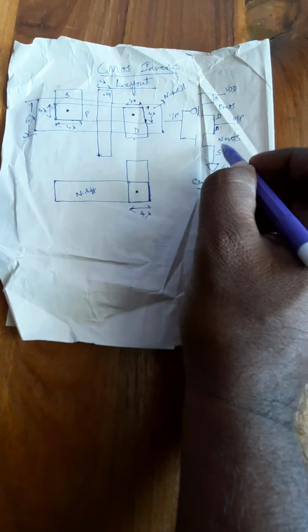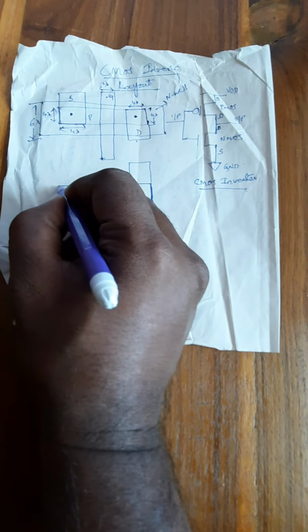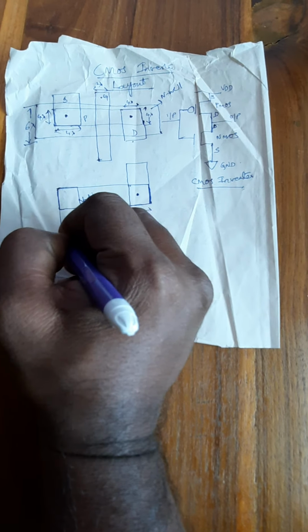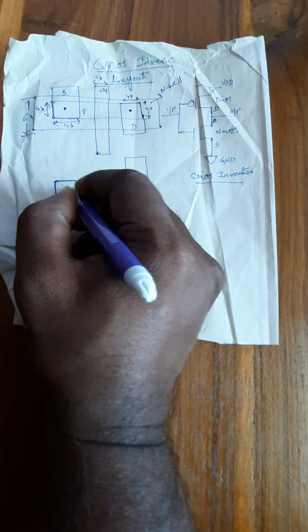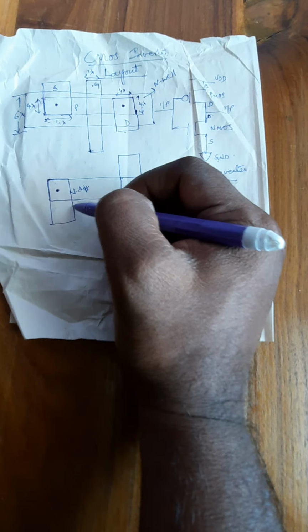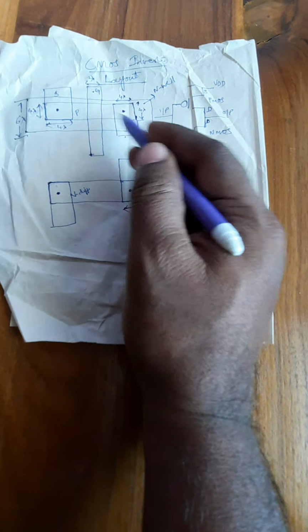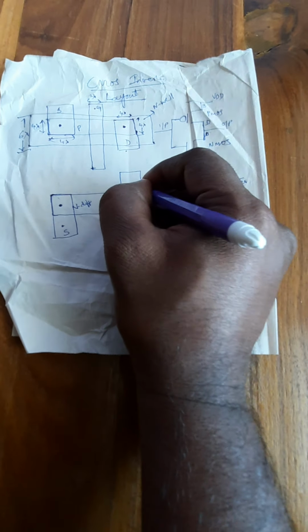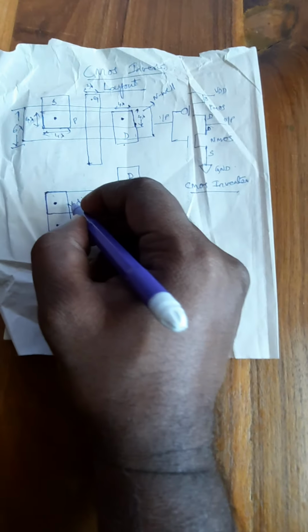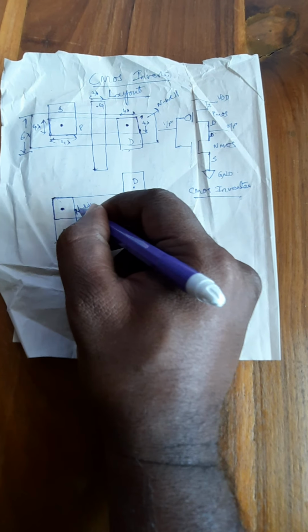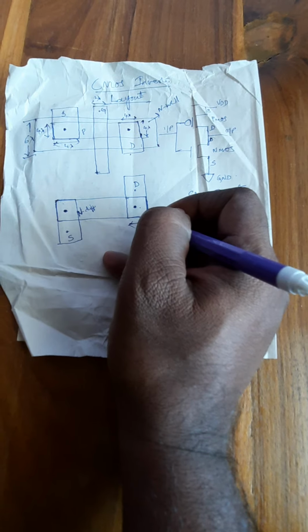Once you complete that, the source of the NMOS is in the downward direction, so I'll take it in the downward direction. I'll put the source terminal with the help of a metal layer. All the source terminal, gate terminal, source terminal and drain terminals have been drawn with the help of metal layers. So this is your source terminal. Once you draw the drain terminals and source terminals on the N diffusion, now you are supposed to use the contacts to make the patching between the N diffusion and the metal layers.